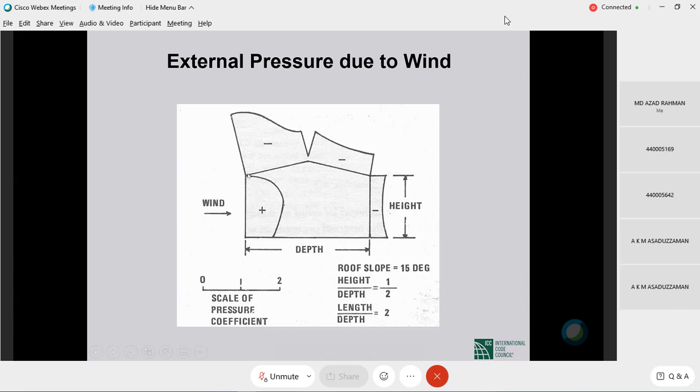And you see very clearly that with a gable roof, the suction here is the highest of any point on the surface of the building. This is a very basic problem in wind design. Because of that very high suction, the windward roof may be sucked up. Wind may suck it up, and when that happens, this wall loses lateral support, and then it doesn't take much for the wall to come down, and that's the end of the building. And that is a very typical failure mode in a windstorm. If you go after a hurricane to look, this is what has happened to many of the buildings. So the first challenge we have in wind design is to tie the roof down to the structure.